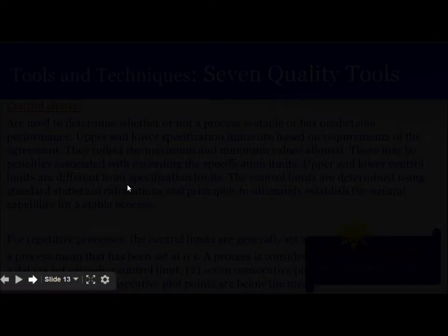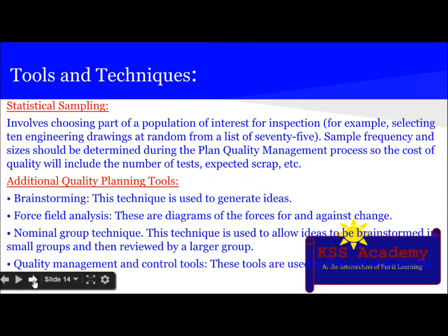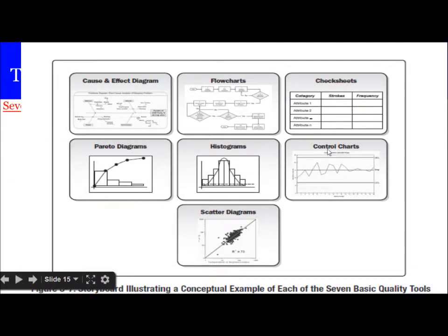So let's look in the picture to understand more. Here is the picture, one second. Yeah, this is the control chart. It is kind of small. This is the mean. This is the upper specification limit, and this is the lower specification limit, and above that is the out of control. So whenever we plot points around the mean, if 7 consecutive points are above the mean or below the mean, then the thing is out of control.